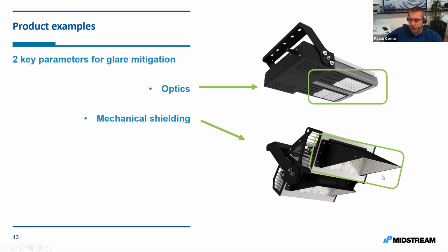But if they're well made, and for example, the ones we use are coated with a highly reflective aluminum surface, they can actually improve the performance of the luminaire compared with the use of solely a symmetrical optic. Because the light that is reflected onto the ground by the visors is light that was going to end up towards the sky anyway.